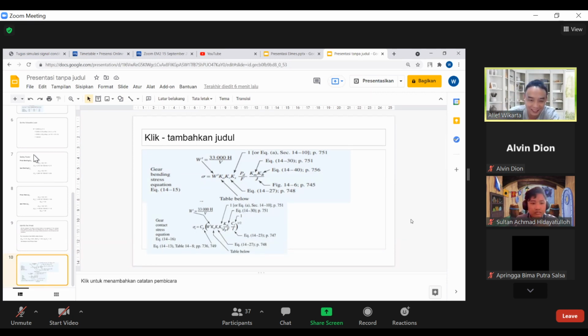You find the stress first by inputting the data, the factors, the geometry, and also the load, and then you use that stress value in your safety factor equation. I think the results should also be the same, because the stress comes from the load.